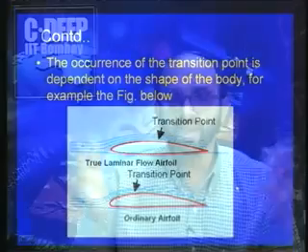So that means the change from laminar boundary layer to turbulent boundary layer depends upon the shape of the body over which the flow takes place, and then the inflow velocity and many other parameters. So that we have to consider while dealing with these kinds of problems. So now, depending upon the problem, we can identify when these changes take place, say from laminar to turbulent, or when this transition starts.